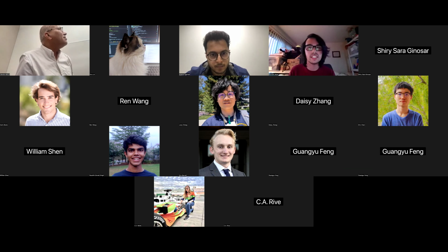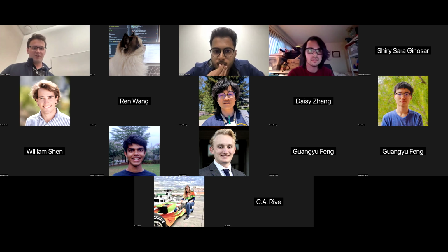Hey, my name is Justin. Thanks for talking to us. I think the new LEAP Hand is super cool. I wanted to probe the measurement of dexterity of the hand using manipulability. I was playing with my own hand during the talk, and I realized that I can't actually move this finger in some of the ways that your hand can actuate the last 2 joints. Do you think that measure of manipulability is the correct one to use? It seems like there's a gap between the conventional sense of manipulability and how human hands are actually able to manipulate objects. Can you comment on that a little bit?